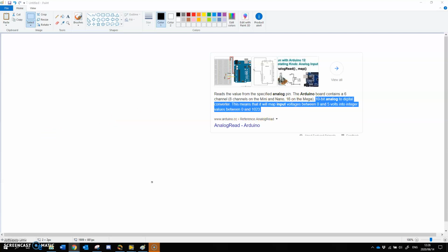That's the 10 bits. So let's just look at the equations, to make this a little bit of maths here. Let's make it a little bit easier. Quantization says this: it's FS divided by 2^b minus 1. They streamline it to 2^b. I don't like the streamlined version. I like the full version. And so what's going to happen here? If that VF is 5 volts, 0 to 5 volts.